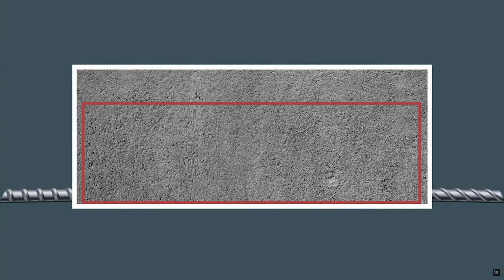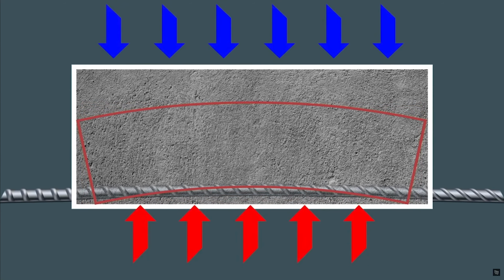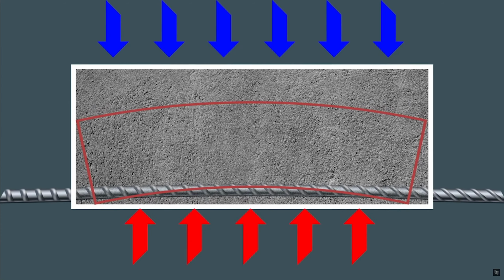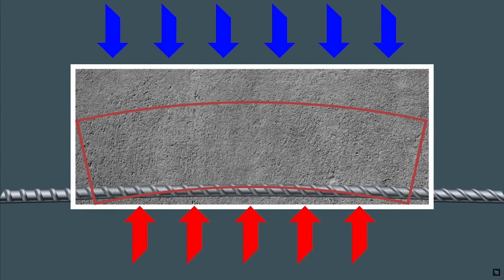And after that concrete has hardened, then we release the tension off of that steel such that now the steel wants to retract back to its original position. But because it now has concrete around it, it is actually pre-stressing before experiencing any load. It's already applying a stress load on the concrete. And so now you have a bow where the beam is going to want to naturally, without any load on it, bow up a little bit.